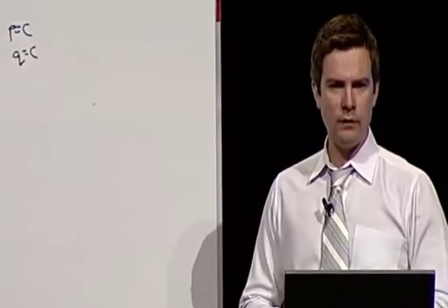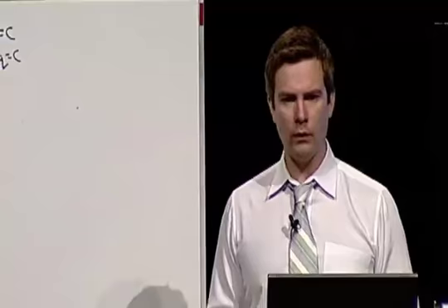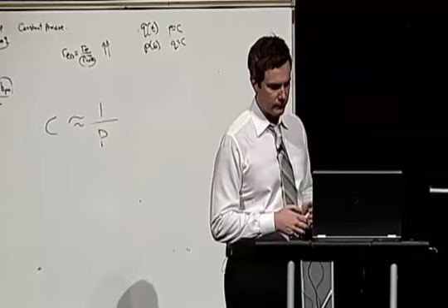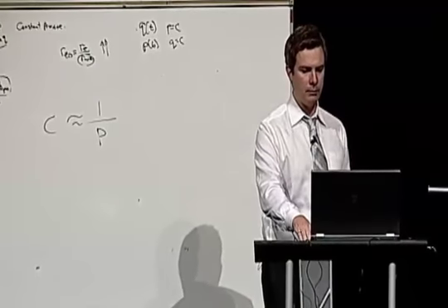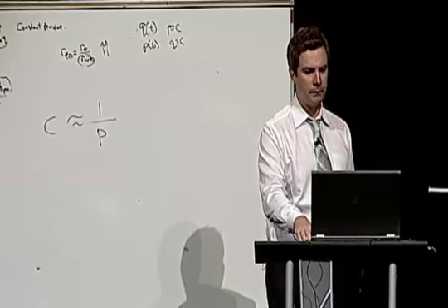Okay? Which is very, very different than the situation we have for oil. For oil, we effectively assume it's constant. For gas, we have compressibility that expands. The compressible energy of the reservoir, of the gas in the reservoir, expands significantly as pressure depletes. So these two are both going to present separate problems that we need corrections for.